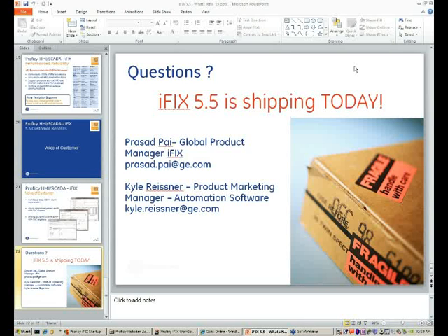Okay. Hey, Carrie? Yes, this is Steve Smith. Hey, something to clarify for those people that are doing the upgrades. The pathing, there was a pathing change. They went from short install paths that existed in the old versions of iFix to a different install path. So when upgrading older versions, if it was C Dynamics or C GE FANUC program files or whatever it was, the default install path for 5.5 is different on a clean install. So you need to take that into account whether or not you're upgrading and leaving your install path the same or doing a new install path.